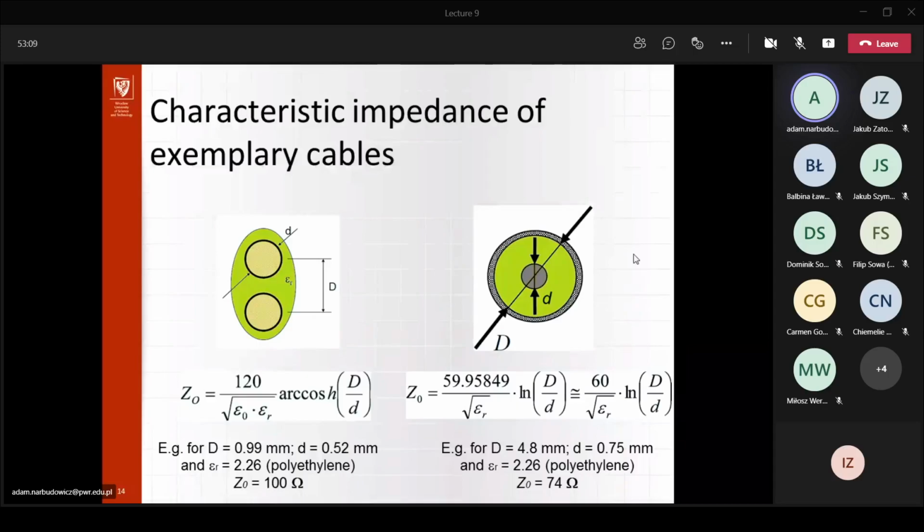Especially when dealing with antennas, you would see that the antenna has a certain input impedance, which is very often, but not always, matched to the 50 ohm standard. And then that, of course, means that you also have to use a 50 ohm cable to connect an antenna with 50 ohm input impedance.